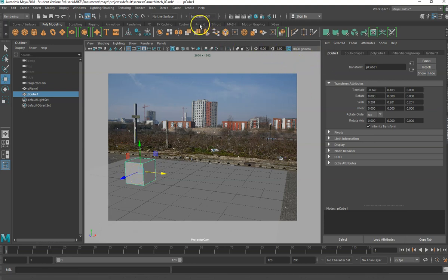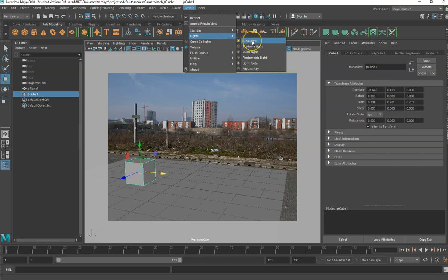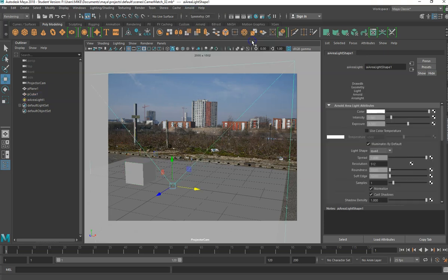To be honest, later on we could do this in a more complicated way and use a skylight and a HDR map to go with it, but for the time being let's just use an Arnold light, and we'll use an area light. Okay, so click area light, and in it arrives to the scene, and again I'm just going to give that a little scale like that.